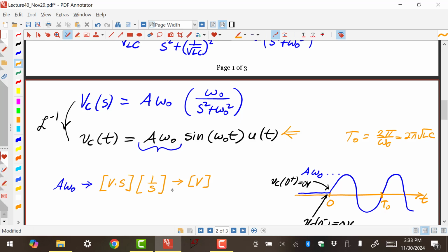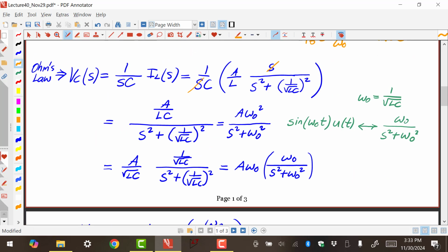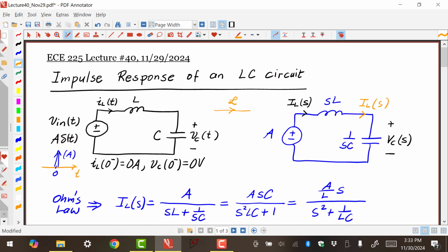So it's very interesting that you have a circuit like this, no resistors, and you hit it with an impulse. And you have to understand what the impulse is doing. At t equals 0 minus, it's not there. At t equals 0 plus, it's not there either. Basically, this voltage source is a short circuit before 0 minus and after 0 plus.